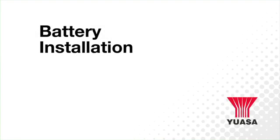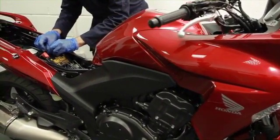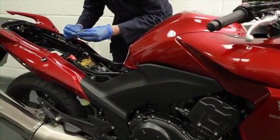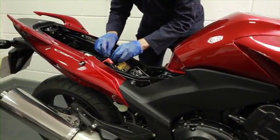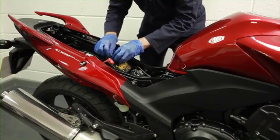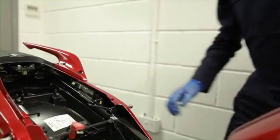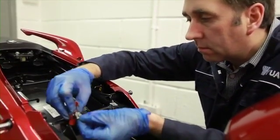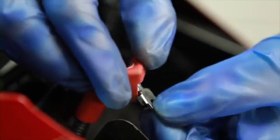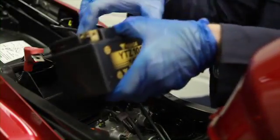Battery installation is a simple process, but incorrect fitting can reduce battery performance and life. If fitted, make sure the rubber dampers in the battery's tray area are in place and are in good condition. These provide cushioning from vibration that could damage the battery. Check the battery cables and connections for any corrosion or damage. Damaged cables or connections can cause charging problems that lead to battery failure.